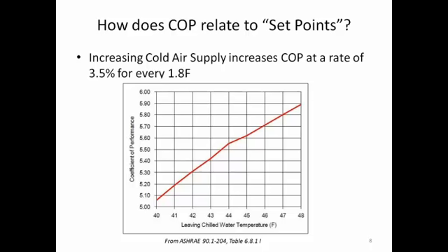The point here is, go ahead. I was just going to say, I think that it's the ratio here that's more important than the absolute numbers here, because the COPs shown are pretty high, and they're idealized conditions here. So I think that those may not be able to be realized in an actual data center. That's true. Probably a device chart for a particular device operating where it's supposed to be operating, but the ratio, the slope, is really the trend is what you can carry forward